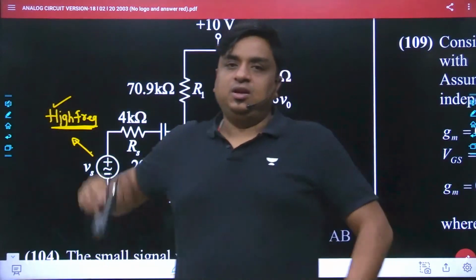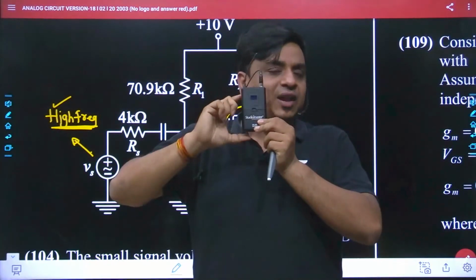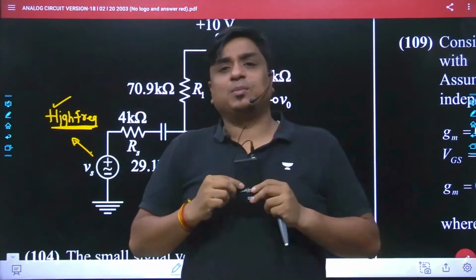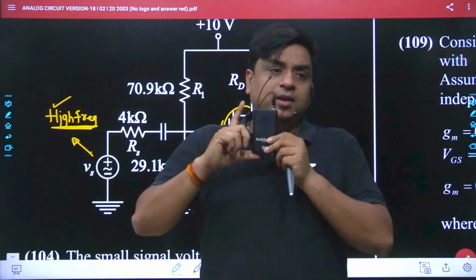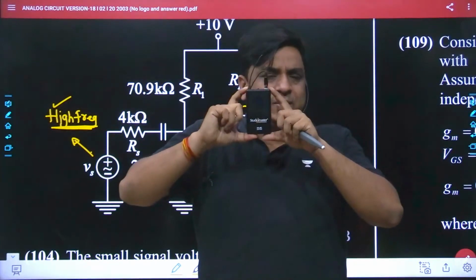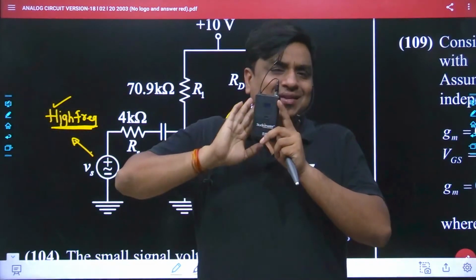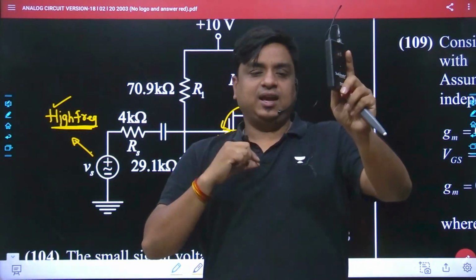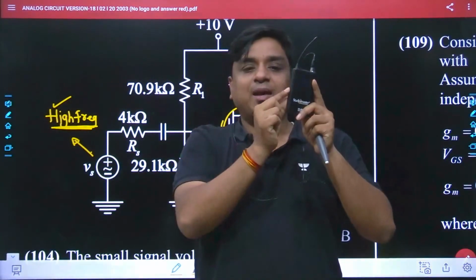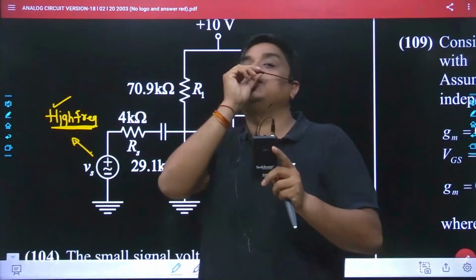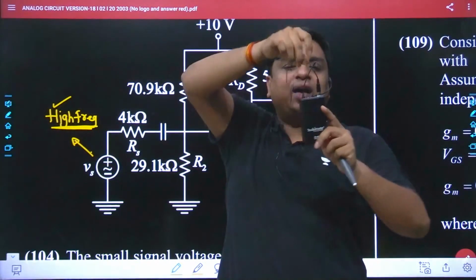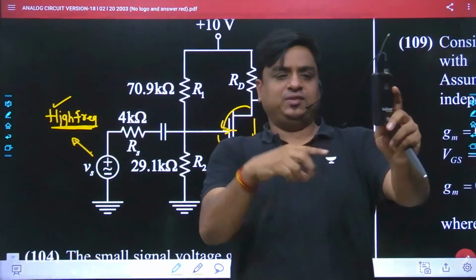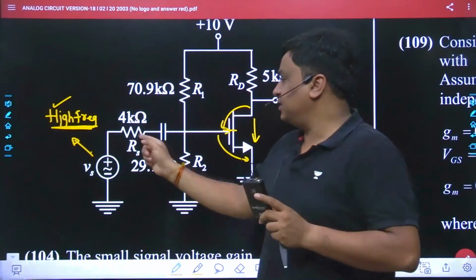My dear friend, see, I have a transmitter. Definitely it will have an amplifier, because the vocal signal that comes through would be in millivolts or microvolts, so definitely I need this amplifier. The amplifier may be MOS based or BJT based. Obviously there must be an internal structure or circuitry which will keep this MOS in the amplification region. So whatever analog signal comes through this wire would get amplified and transmitted. All the way this signal goes through the wire to this system. So this input is nothing but the input of the source. Obviously the length of this wire carries a certain amount of resistance, and that is nothing but the source resistance.